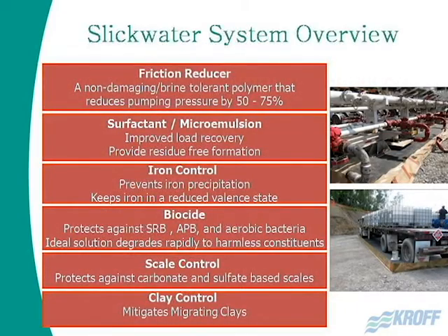These are the types of chemicals. Everyone asks, what are they pumping underground? Really not that harmful, pretty innocuous. Friction reducers to reduce the amount of pressure necessary to place the water and sand. Surfactants, which is a fancy name for soap, or microemulsions, that reduce the surface tension, allowing more water to come out of the formation, and more gas. Don't want iron, don't want bacteria, you don't want scale, you don't want clay fines. So these are typical slick water chemicals that are used in the gas fracturing process.